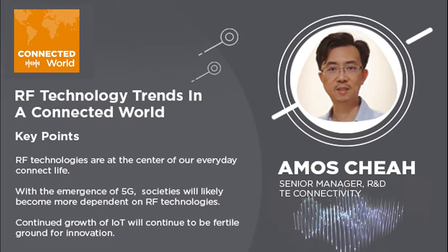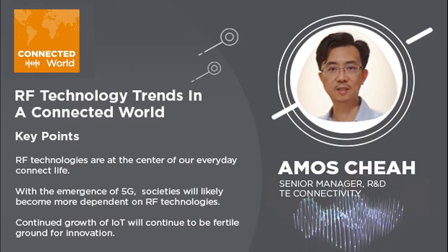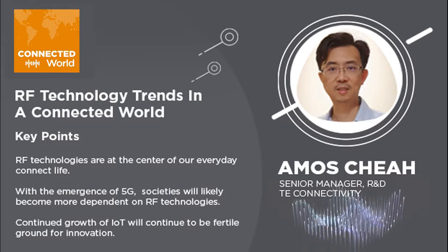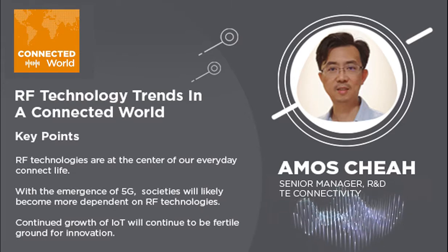So then, a time varying voltage and current generate electromagnetic energy that propagates in the form of waves. So we can wirelessly transfer signals by manipulating and interpreting this wave. And while electromagnetic waves or RF frequency is the dominant form of wireless communication, because the only alternative is the use of light, RF is much more versatile because low frequency electromagnetic waves are not blocked by any solid objects.